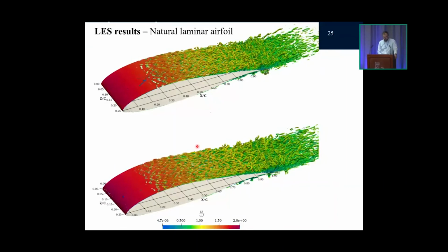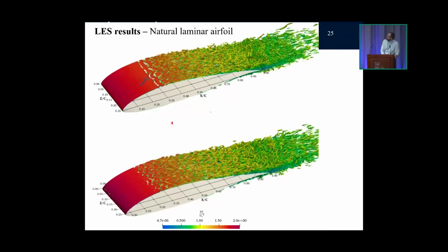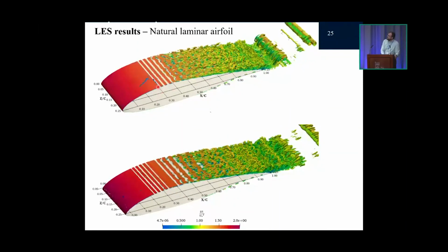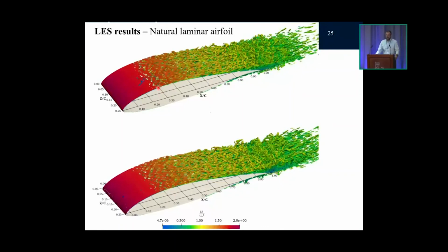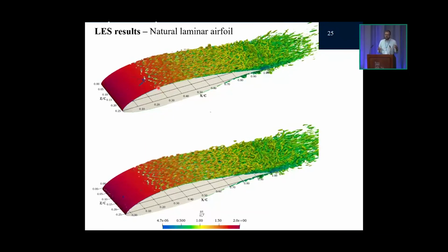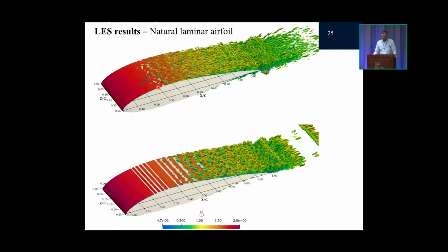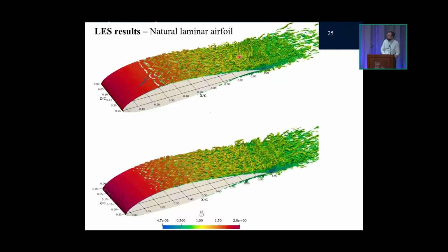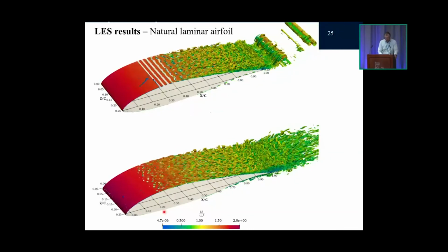These animations are a little bit blocky, but what we see is again an amplification of disturbances that result in a streamwise grouping of spanwise vorticity that then interact, produce hairpin structures that undergo mutual stretching and tilting operations, fall apart into three-dimensional structures, and then form these hairpin vortices as they evolve over the airfoil. And what does the droop do?